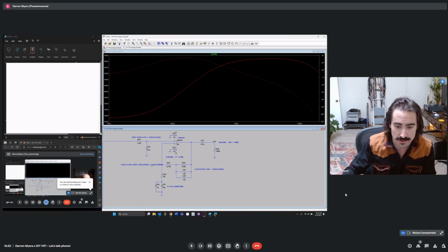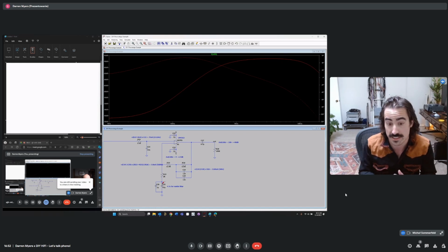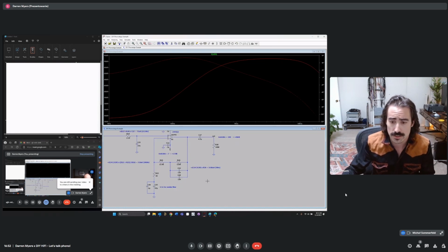And so that's where you come up with this time constant right here, because the time constant is the resistance times the capacitance. So it's RC. But we've created a more complex equation just because of how these other components interact with this R value. But this is the C value, and that is the R value for this time constant here. Okay? Makes sense. So moving on to our 50 hertz, now we're looking at it being this value right here.